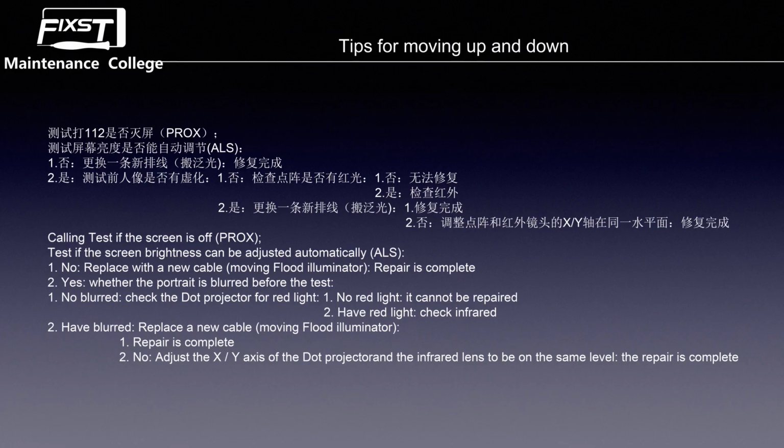Okay, this problem is finished. And you need to remember, if the dot projector, flood emitter, or infrared camera, one of these three components is damaged, you don't need to repair it, because these three components are all tied to the CPU. If this component is damaged, it is like the CPU being damaged. If these components are cracked, it is like the CPU being cracked. Cannot repair it. Don't take so long to repair it.